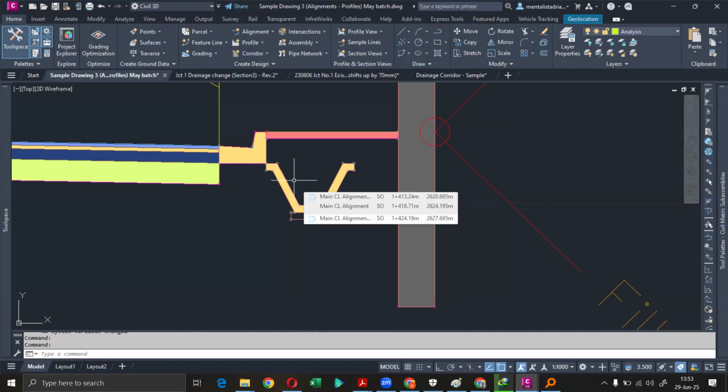They need to have a drainage system on one side, and it can't be on both sides. It has to be one side. You might have some crossing currents, but again, I don't recommend having water just cross over the road, because it messes up the road.